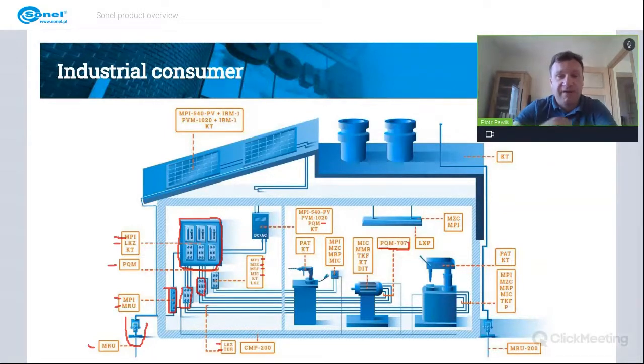For example, we can have elevators, which are very high load devices, and they work non-continuously, so they can mess up our power quality, and we wouldn't like that. We can check, for example, the lighting, especially if we have LED lights, they can put some harmonics into our network, so we can check each component of the network with the power quality meter.